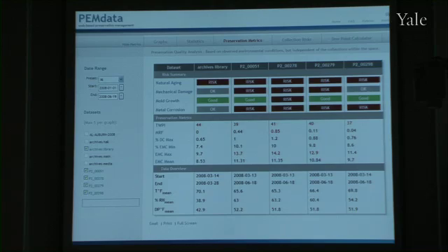All right. So when you have temperature and humidity data, a lot of people think that they're then able to understand what the collections are experiencing. Yeah, right. That's what we spent 25 years of research to try to figure out: surely there are ways to take that basic information about temperature and moisture and then derive something more meaningful, that helps us understand whether it's good or bad, or precisely how good or bad it is for collections. So here's a kind of console view that you might see. These are the different spaces.